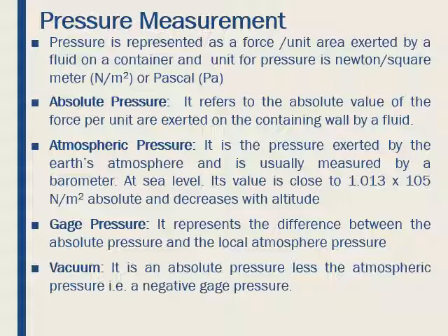Generally, high pressures can be conveniently expressed in kilonewton per meter square, while low pressures are expressed in terms of millimeter of water or millimeter of mercury. Pressure is the action of one force against another or over a surface. The pressure P of a force F distributed over an area A is defined by P is equal to F by A.